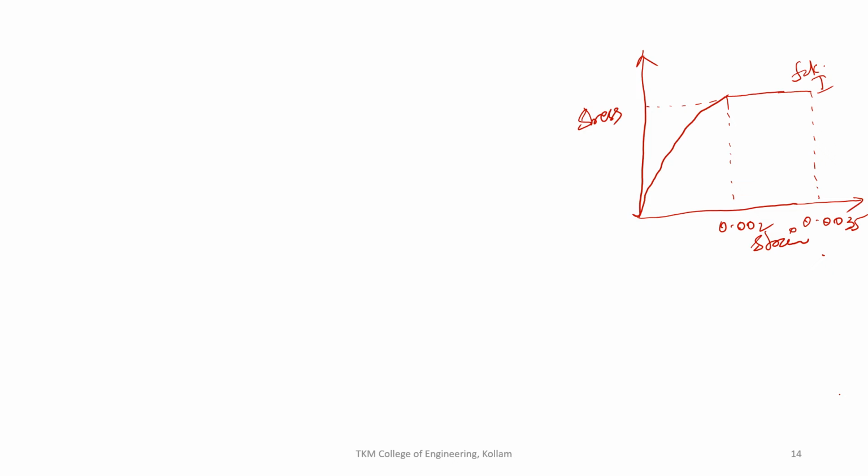Now, in order to take care of the field and laboratory differences, we will divide it by a factor of 1.5, such that we get a curve like this. We will get curve 2, that is FCK divided by 1.5, that is 0.67 FCK.